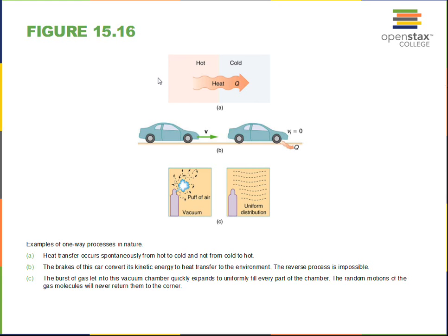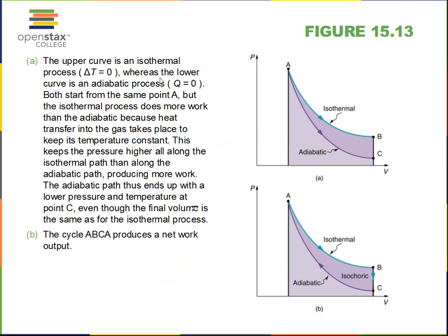So just maybe to go back just a little bit here, there are mechanisms or ways of calculating the work done on an isothermal path. It involves a logarithmic calculation, and the work basically is how many moles are in the gas system times the gas constant multiplied by the temperature in Kelvin times the natural log of the ratio of final volume divided by initial volume.